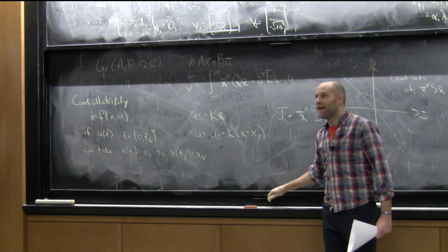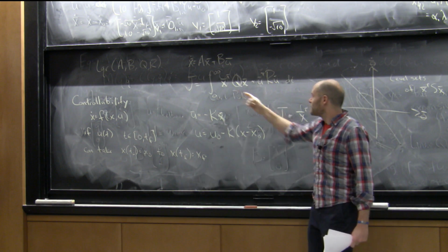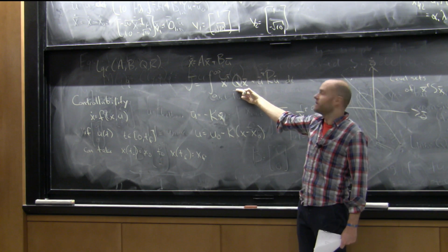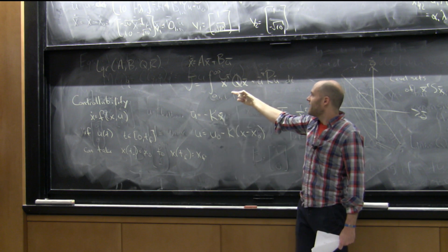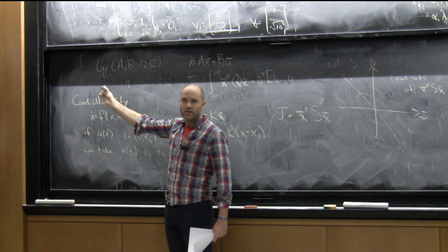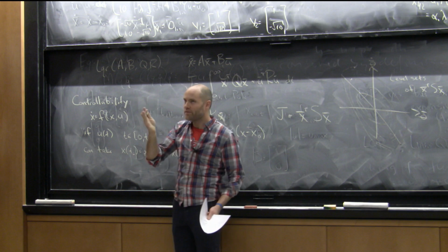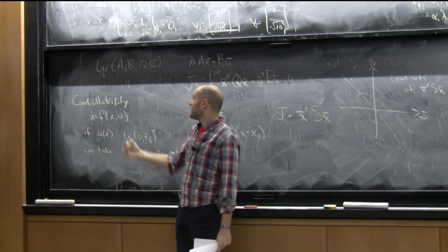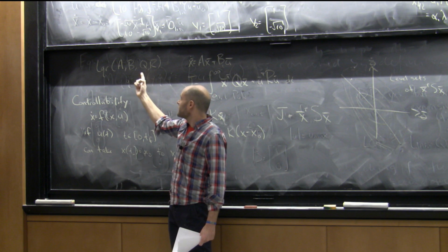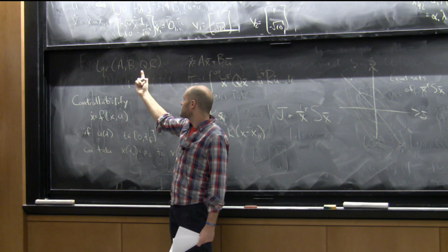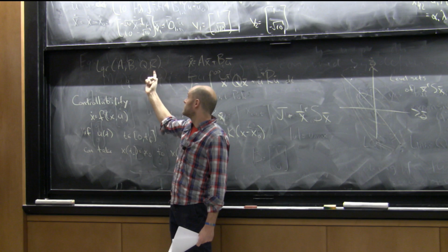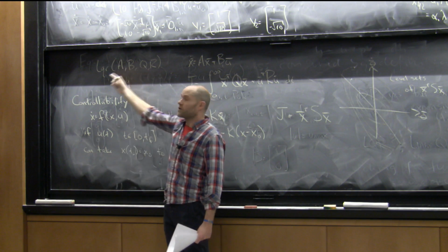Now, advanced fact here, if you care, it makes this a very nice piece of machinery, okay, that there's a lot of different stabilizing controllers that I can generate. I might want some that converge really fast, or some that use less energy, or whatever. There's a lot that I can do by just twiddling Q and R. And it's really nice to have a function that you can call that returns almost instantly, that for any positive Q and positive R, and Q can be 0 but R cannot, it's going to return a stabilizing controller.